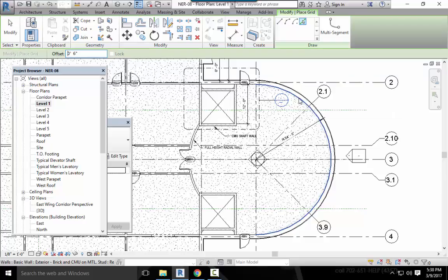Pick the finished inside face of the radial wall. Make sure the alignment indicates where the grid will go. The grid bubble lands on a congested area. Fix that by adding an elbow and adjusting the bubbles as shown by grid G near the top of figure 8.20.